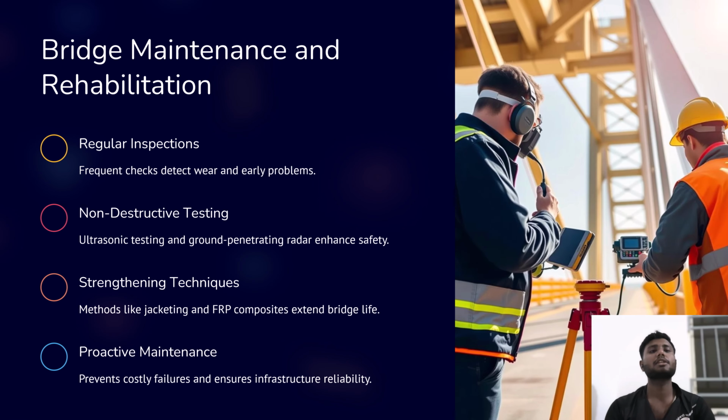The last topic is bridge maintenance and rehabilitation. In regular inspection, we have to inspect bridges regularly, so we get a better life of the bridge. Frequent checks detect wear and early problems. Next is non-destructive testing. There are various tests in the market, and non-destructive testing is one of them. Ultrasonic testing and ground penetrating radar enhance safety. It is an advanced technology to detect bridge quality.